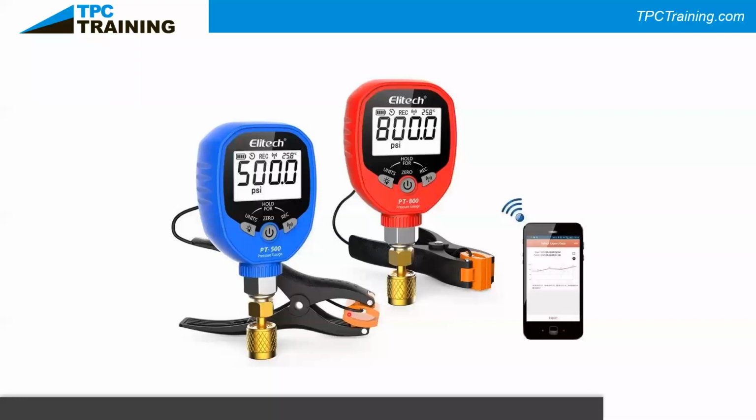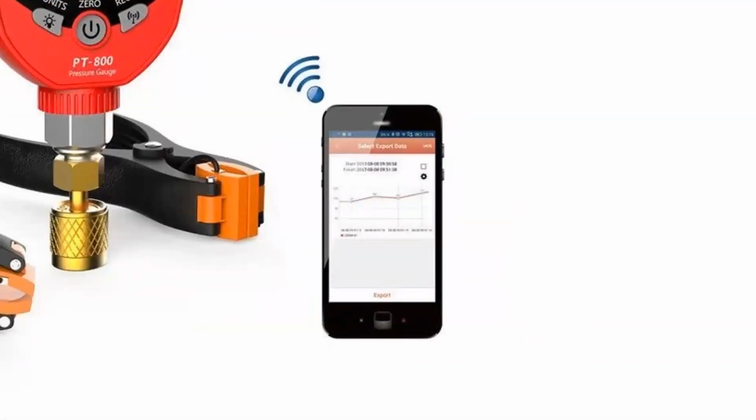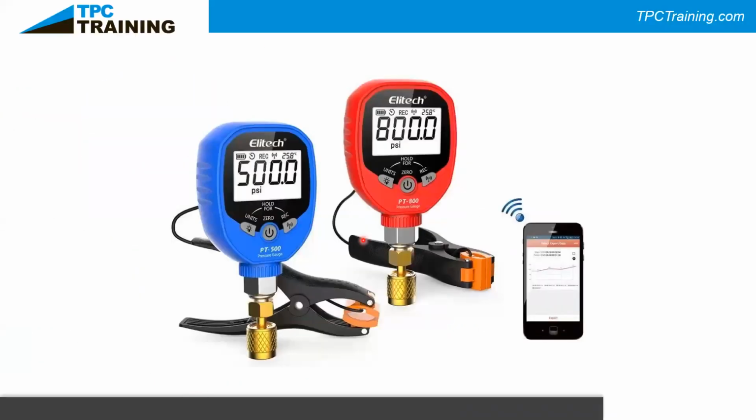And then I take these temperature probes and I clip them onto the liquid line and the suction line of my refrigeration system. And then I could be down in my truck eating lunch and say, what are my system pressures? And what is my superheat and subcooling? And everything's Bluetooth right to your phone for you. Now, the problem is when you have modern technology like that, obviously you have more cost involved. So if you're starting out in the field, it might not be a good idea to jump right into something like this until you get comfortable with what we call analog gauges.